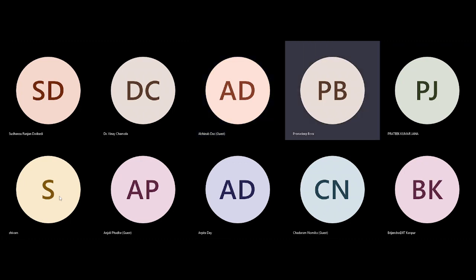Correct. Like, let's say for a smaller design, you can verify it in the implementation, right? You can see all the nets and LUT cells, and you can see that everything is implemented perfectly as you need. That is the interface you'll get. But for a bigger design, it is quite difficult. So for that, we need to use debug probes. That is the last part.